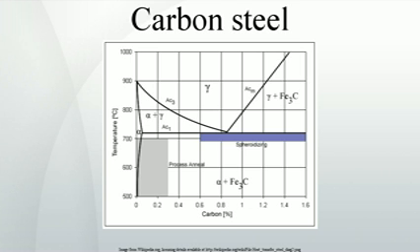Heat treatment. The purpose of heat treating carbon steel is to change the mechanical properties of steel, usually ductility, hardness, yield strength, or impact resistance. Note that the electrical and thermal conductivity are only slightly altered. As with most strengthening techniques for steel, Young's modulus, elasticity, is unaffected. All treatments of steel trade ductility for increased strength and vice versa.